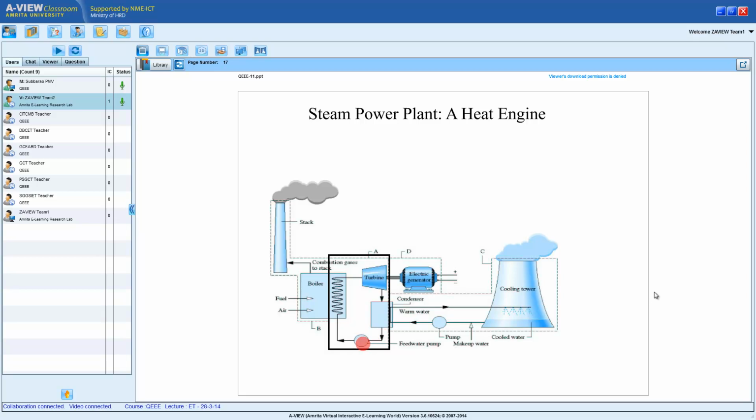All the 4 control volumes are connected head to tail, the tail of one connected to the head of the other. If I draw a boundary, you see this is the beauty of this one. Nothing crosses the boundary. No mass flow crosses the boundary. It means if I develop a cycle using control volumes, the complete cycle will be a control mass. No mass crosses the boundary. What can cross? You can imagine here.